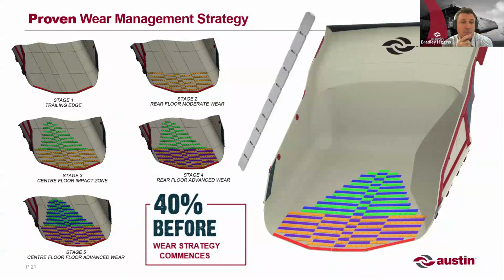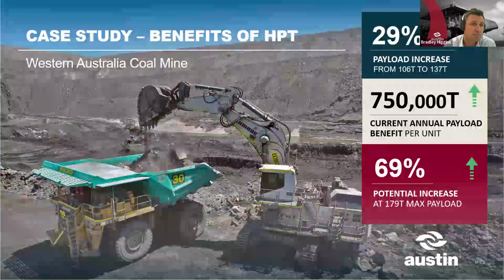Again, spoke before around some of the maintenance strategies. I won't go into too much detail, mindful of time, but as you can see here, we do have different levels of wear maintenance strategies that we can help apply to the linerless truck bodies we build, enabling you to sweat that asset even further. So these wear strips are designed to be welded in once and not to be gouged out, reducing half the hot work and that high risk work of gouging out wear plates.